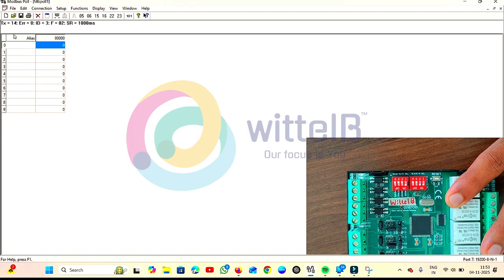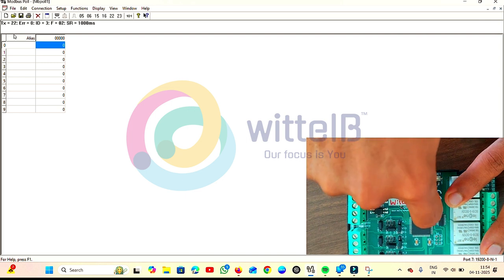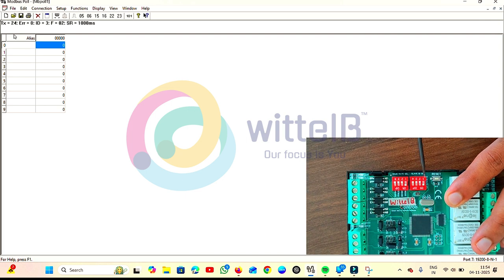So now I need to set the slave ID as 5 and the baud rate as 38400. So now I will hide the first pin and the third pin of the slave ID. That means 4 plus 1 will be 5. Now I need to set the baud rate, that is 38400, which is the second pin. So I will hide this pin and now I will press the reset.